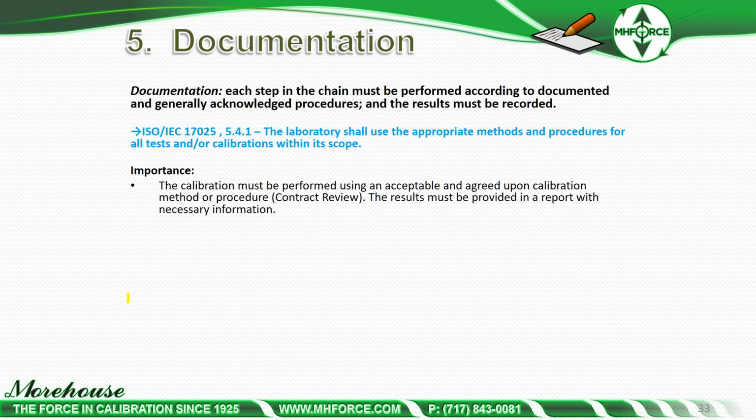So the better thing to do is say, hey, I need this thing. I'm using this. Maybe I'm using this load cell increasing only. I'm concerned with my non-linearity, and I'm concerned with repeatability. I'd recommend E74. I think it will take away a lot of that error, but I know that's not acceptable to everybody. So yeah, get the specifications that you need, put it on the contract, and be sure to tell the laboratory what those are.